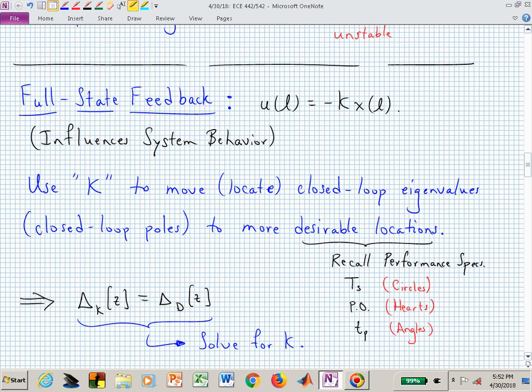But those different shapes should inform our choice of what we want our system to behave like, and the angle that those poles make. Now we're really focusing on 2 dominant poles. If we had a fifth order system, what's a quick way for the final exam to select the locations for those 5 poles?